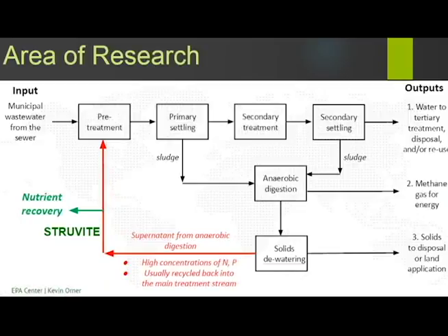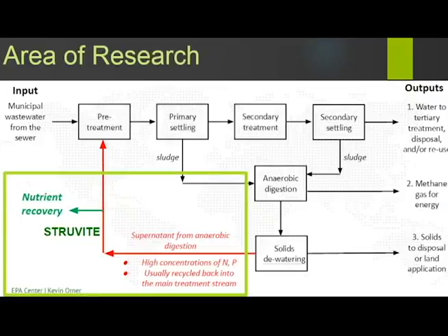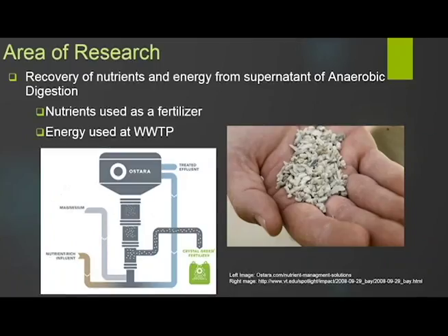Thrust 1C is focused on resource recovery at centralized wastewater treatment plants, and more specifically at the side stream treatment. To get a better idea of what I mean by side stream treatment, the figure displays a standard layout at a wastewater treatment plant. The effluent of anaerobic digestion is dewatered. The solids are disposed while the liquid, or supernatant, is recycled to the head of the plant. This is called the side stream. This supernatant has high concentrations of nitrogen and phosphorus, which makes it a preferable location for nutrient recovery.